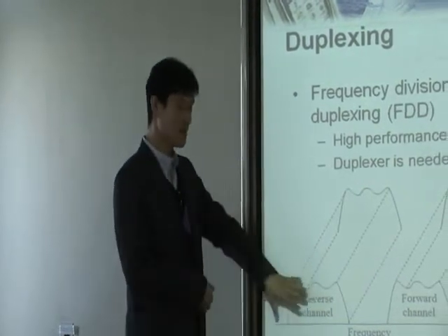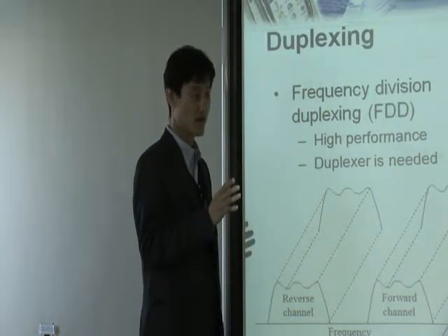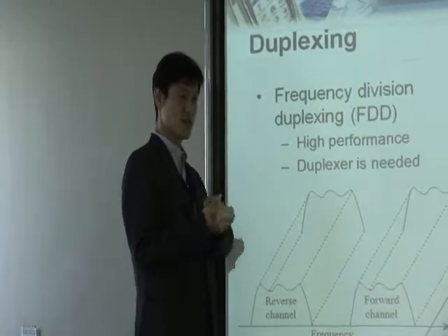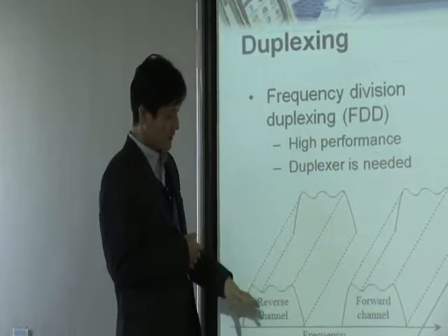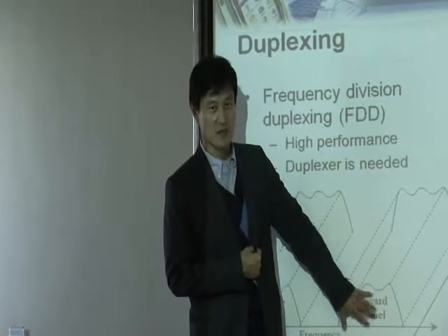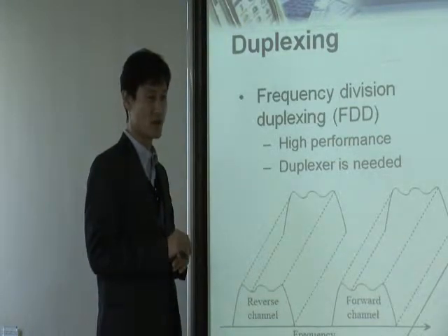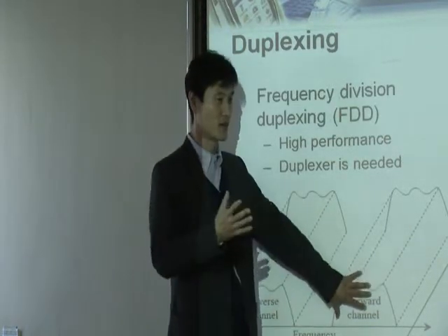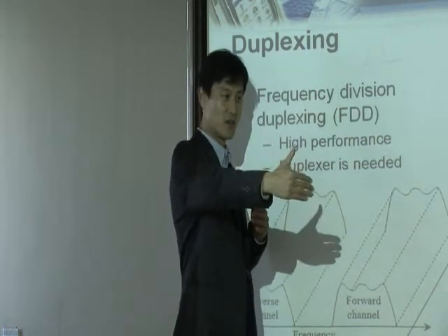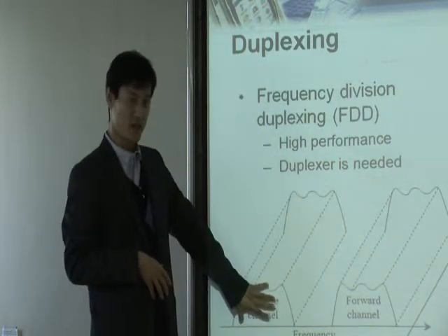Why do you want to make uplink transmission go further? This is uplink. Because this is downlink, right? Downlink is what the base station transmits. The base station never worries about the power, never worries about the cost. They can have so much power. So if the base station's transmission does not go further, then I can increase the power. No problem. This is uplink, right?